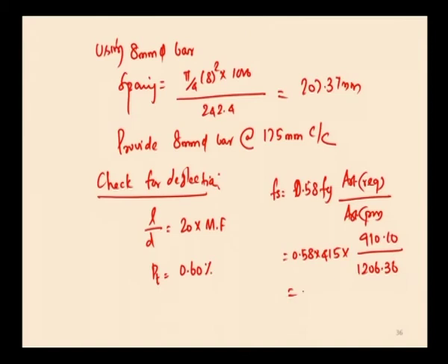So, the stress in the steel here is 131.60 Newton per millimeter square, and the modification factor here is 1.8 by referring to figure 4 of IS 456-2000.